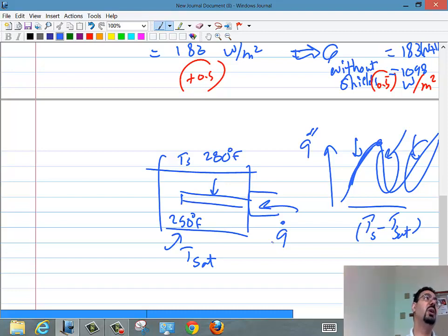But if the water is not there, why? Something happened, the water is out of the reactor. It's just surrounded by air. Well, air natural convection is not the same as the boiling mechanism that was taking a lot of latent heat. So as a result, there is not enough mechanism to disperse that Q. So the element will get hotter and hotter, right?